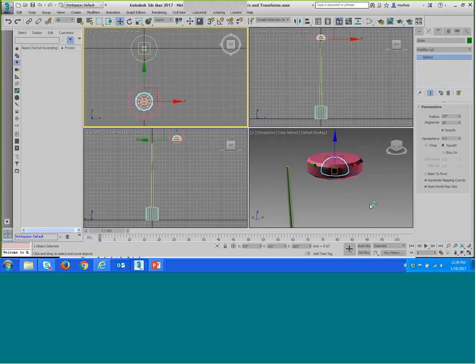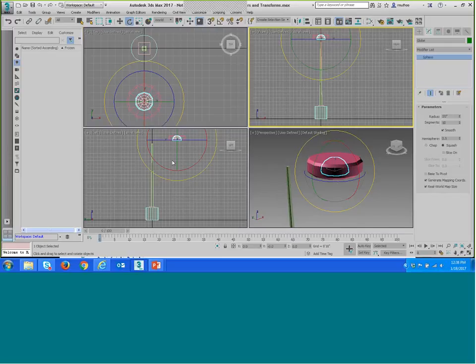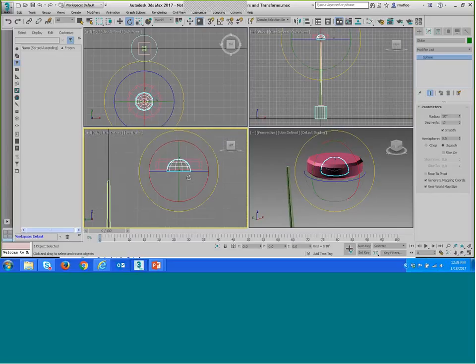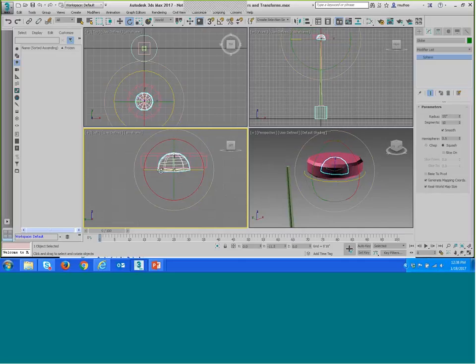We will use the rotate tool to rotate the globe, right here, and you can see the rotate gizmo. Maybe using the left view, I can show you better. I can use one of the rotate gizmo axes to move it in one direction or different directions. You can move it like this, or in this direction or any other direction.